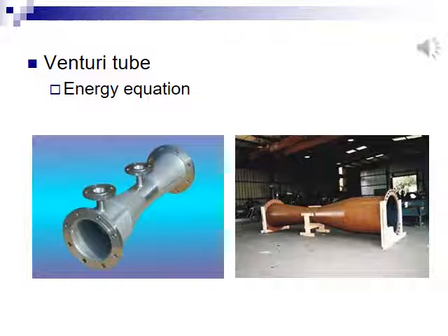Next is a device to measure discharge rate. This is a Venturi tube designed by an Italian physicist, Giovanni Battista Venturi. A Venturi tube includes a convergent entrance, a cylindrical throat, and a divergent outlet. Fluid passing through the tube speeds up as it enters the throat, and the pressure drops. We will use the energy equation to explain its cleverness.